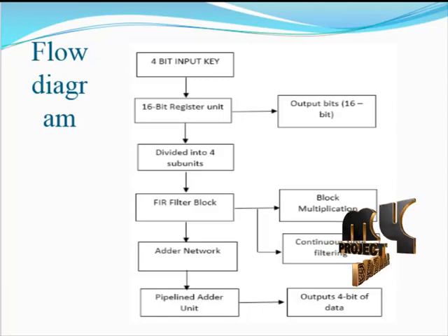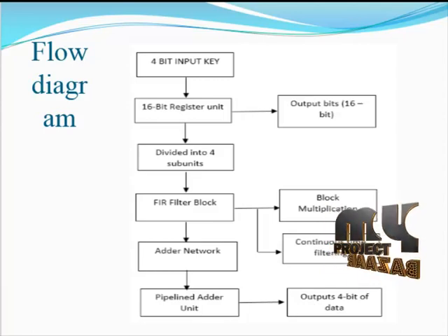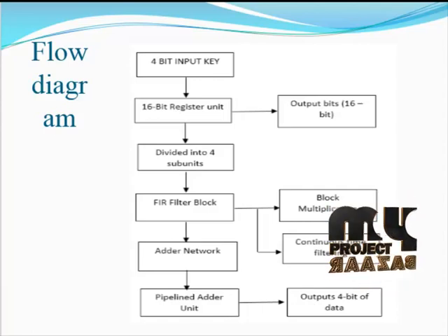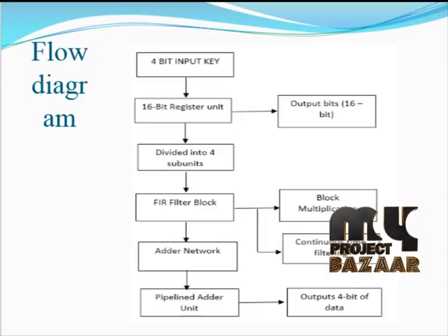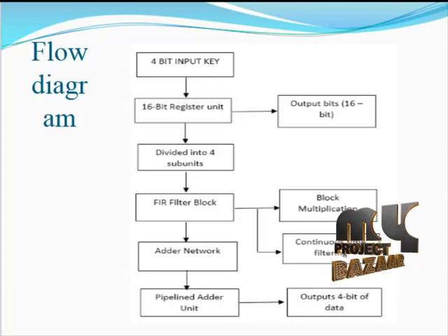The block processing method is popularly used to derive high throughput hardware structures. It not only provides throughput scalable design but also improves the area delay efficiency. The derivation of block-based FIR structure is straightforward when direct form configuration is used, whereas the transpose form configuration does not directly support block processing. But to take the computational advantage of the MCM, the FIR filter is required to be realized by transpose form configuration. Apart from that, transpose form structures are inherently pipelined and supposed to offer higher operating frequency to support higher sampling rate. The FIR filter block consists of block multiplication technique and MCM.